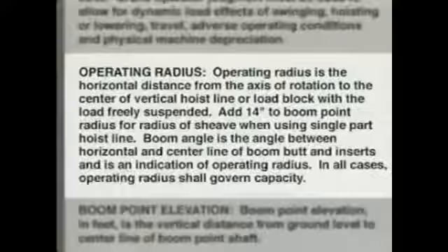With the necessary connections made, the rigger signals the crane operator to test lift the load a few inches. Once the rigger is confident that the load is secure and properly balanced, he signals the crane operator to start moving the load to its destination. Along the way, the rigger and the crane operator are careful to watch for personnel in the area and for obstructions such as overhead power lines.